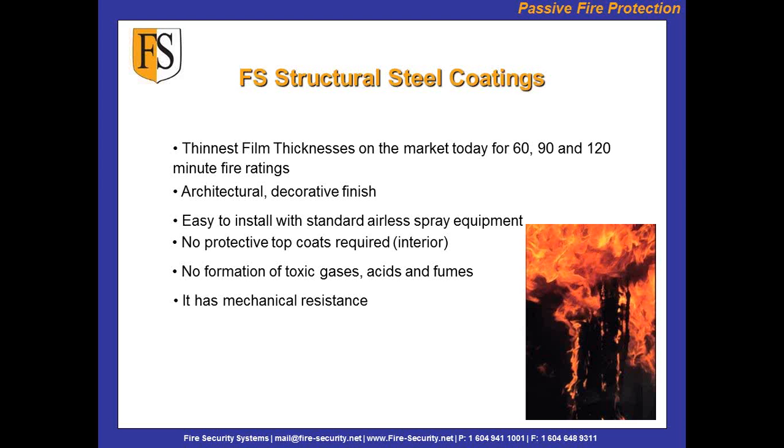If it's a water-based coating, we would put a protective FS84 top coat layer over it just for travel, because it might sit on the road for 7 days in rain. So that intumescent interior water-based coating needs to be protected.